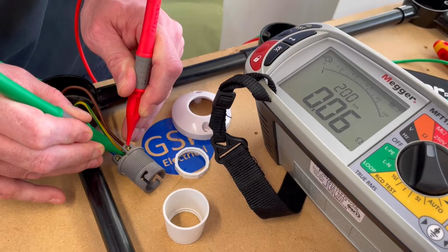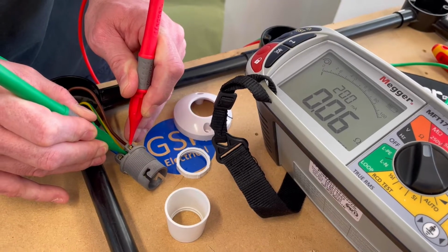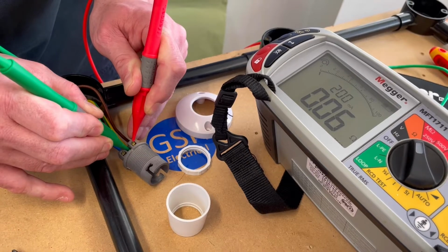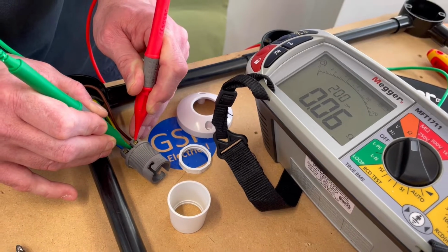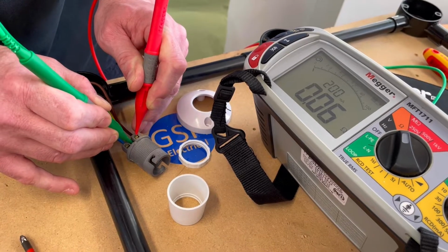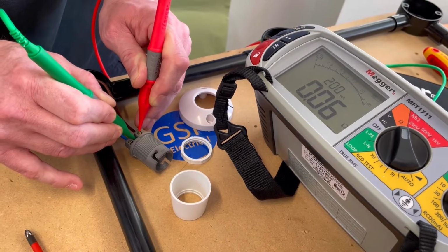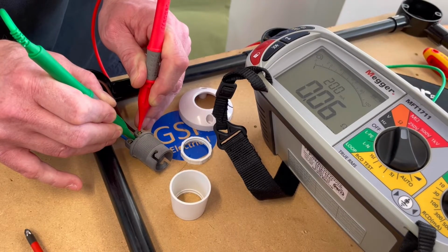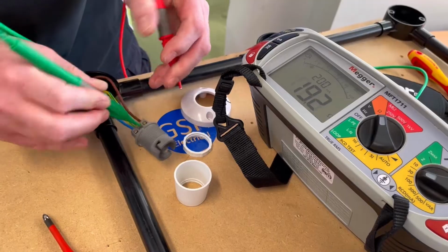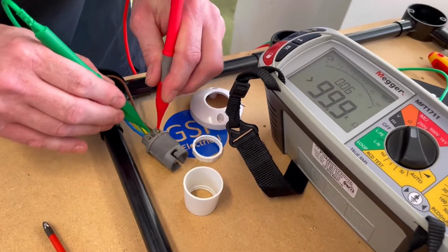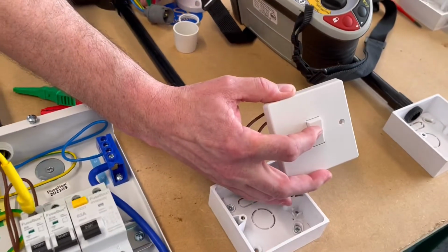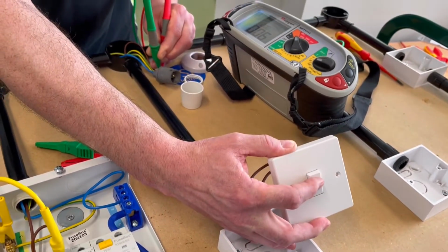And I've got a reading of, when it settles down, 0.06 of an ohm. So that suggests that we're getting a resistive reading, a completed circuit. We need to remember that reading, but at the same time, we also need to operate the switch. So at the minute the switch is closed, we have a low reading and therefore it would be in the on position. But in order to do our polarity check, we need to make sure that we operate that switch. So I'm going to operate the switch. If I put my hands in a more comfortable position, I come down to here to operate the switch. So down at the minute it's on, so that's quite logical.